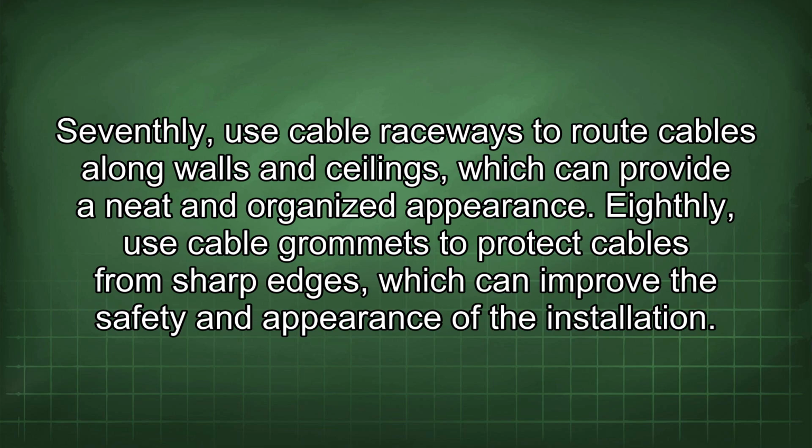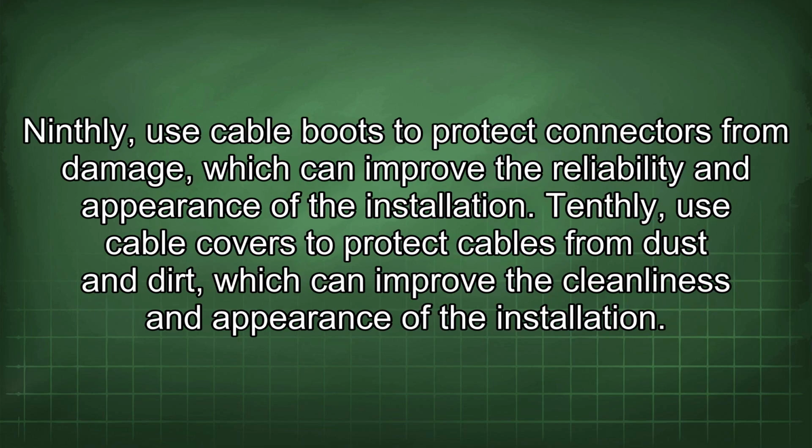Eighthly, use cable grommets to protect cables from sharp edges, which can improve the safety and appearance of the installation. Ninthly, use cable boots to protect connectors from damage, which can improve the reliability and appearance of the installation. Tenthly, use cable covers to protect cables from dust and dirt, which can improve the cleanliness and appearance of the installation.